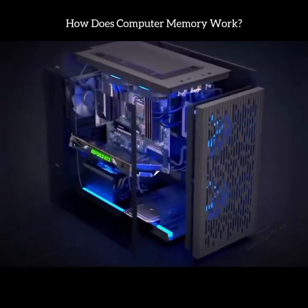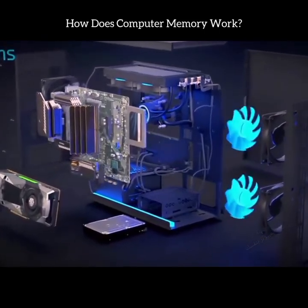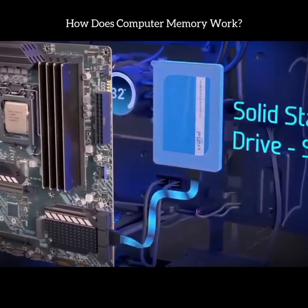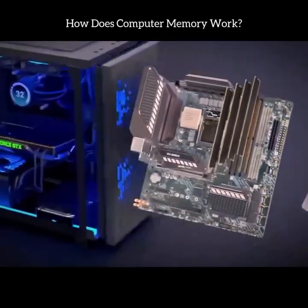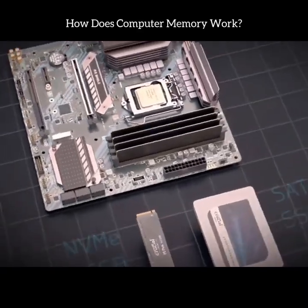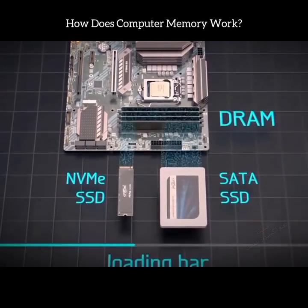Have you ever wondered what's happening inside your computer when you load a program or video game? Well, millions of operations are happening. But perhaps the most common is simply copying data from a solid-state drive or SSD into dynamic random access memory or DRAM. An SSD stores all the programs and data for long-term storage, but when your computer wants to use that data, it has to first move the appropriate files into DRAM, which takes time, hence the loading bar.